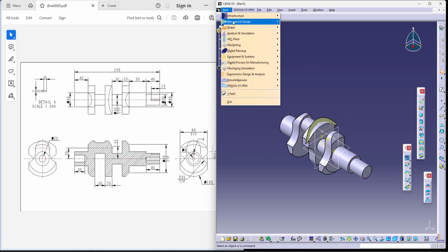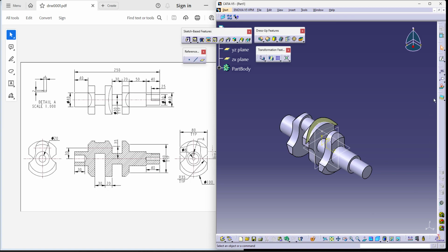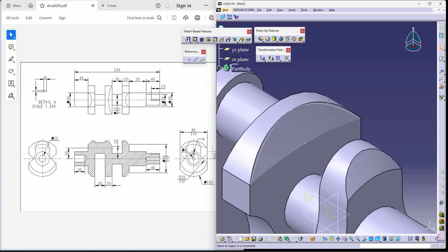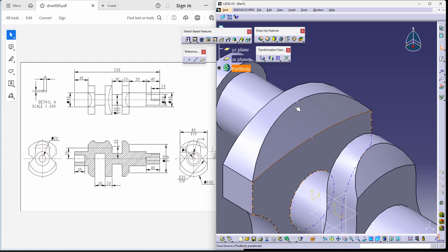And to remove this, we can go back into your part design and start using your split command. Split is a very easy command to use. You just have to select what is your splitting element. When you say OK, it tries to split it. You can hide the surface and I will show you how the shape looks. This is the shape. You can hide the curves as well if you want, and the points.